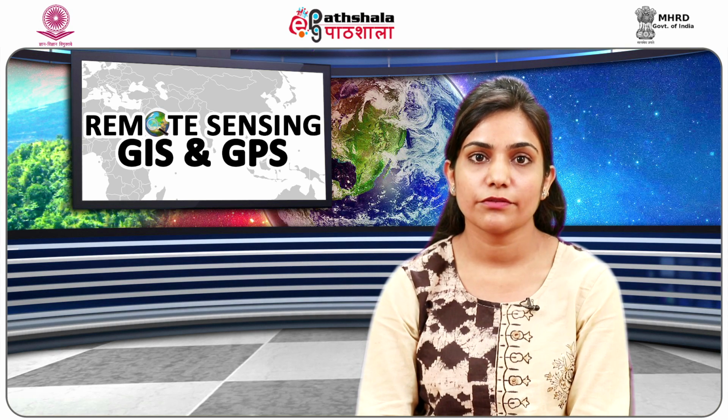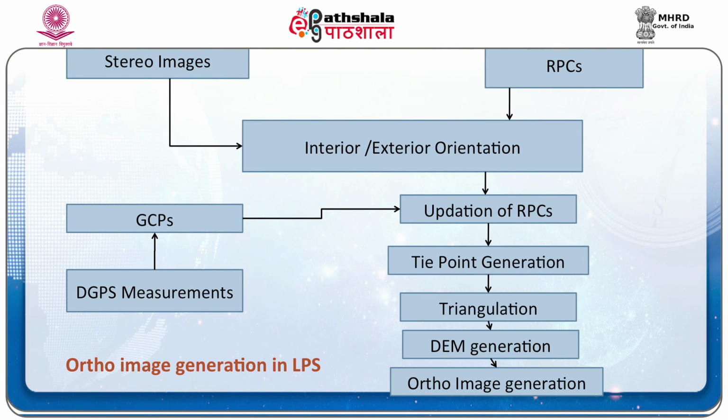Figure number 9 shows the flowchart for ortho image generation. To generate an ortho image, we follow these steps. First, we need GPS control points with aerial photographs, that is stereo pairs with RPCs. RPCs provide a compact representation of ground to image geometry. Next, we perform interior and exterior orientation. Interior orientation is concerned with the determination of a set of parameters for the transformation from pixel to image coordinates. Exterior orientation represents a transformation from the ground coordinate system to the image coordinate system. The exterior orientation is the position and orientation of the camera when the image was taken.